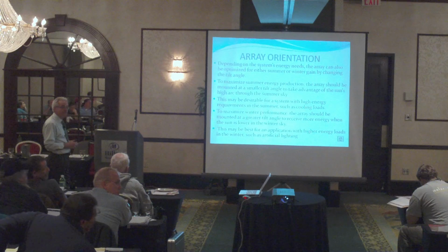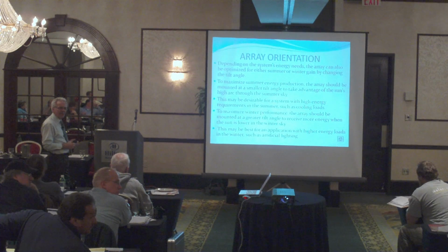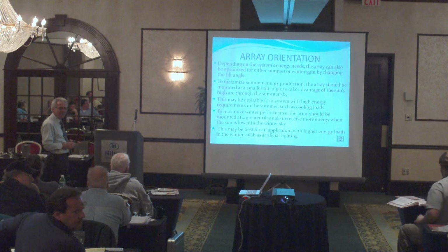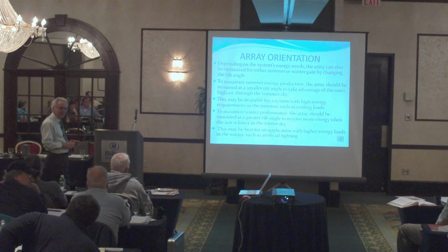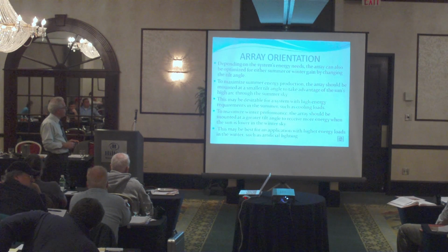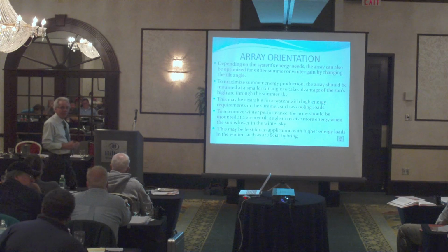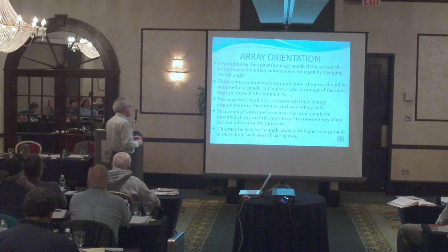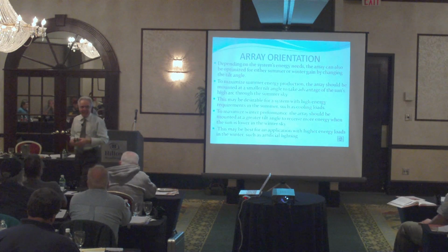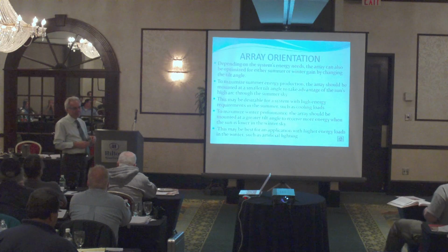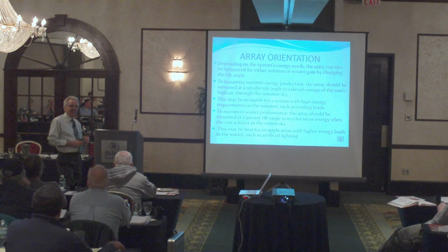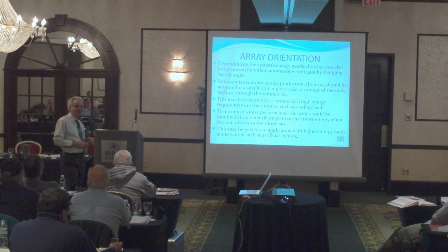What's the percentage between the winter and summer? If you're going to get up on the roof and adjust your tilt angle, what percentage of power are you going to lose? That's a good question. It turns out 10%, 15% extra if you go up there seasonally and adjust the panels, or maybe you're going to get 2%?